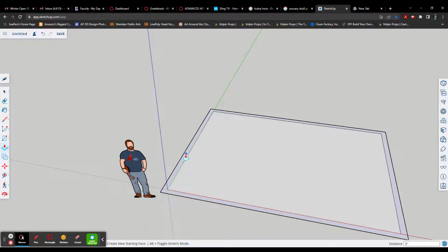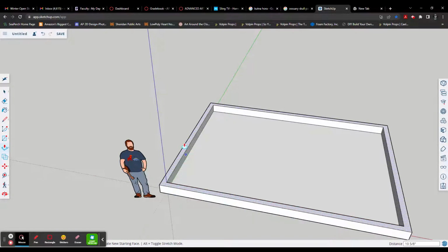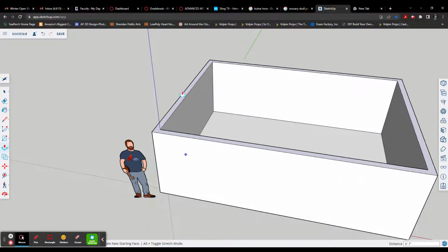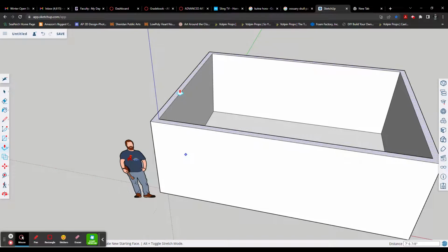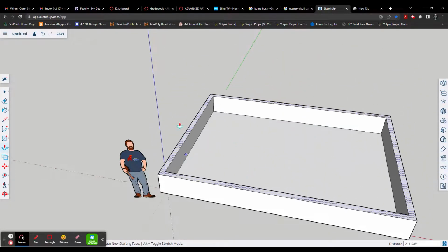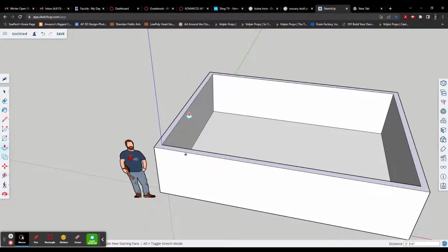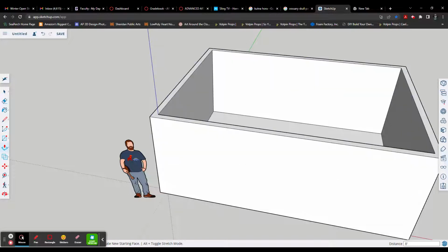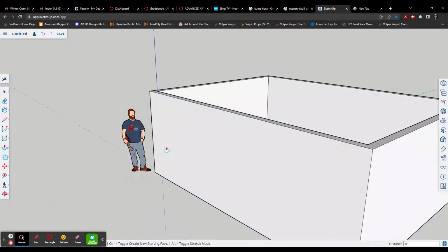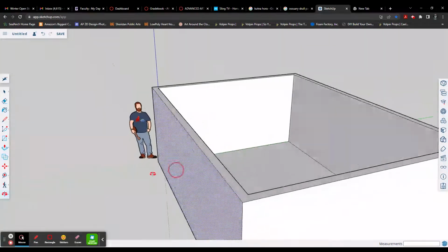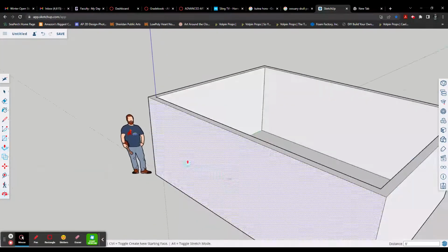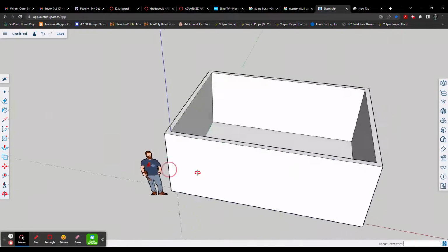Okay, so this 6-inch space, if I click it with the push-pull tool, which is P on the keyboard, it's also on the left-hand side underneath, you can see that I can now pull that thick wall up. Typical floor on the interior in the United States is 8 feet, so I can just type in 8 apostrophe, hit enter, and I now have an 8-foot tall, 6-inch thick wall. All right, so I have my volume.